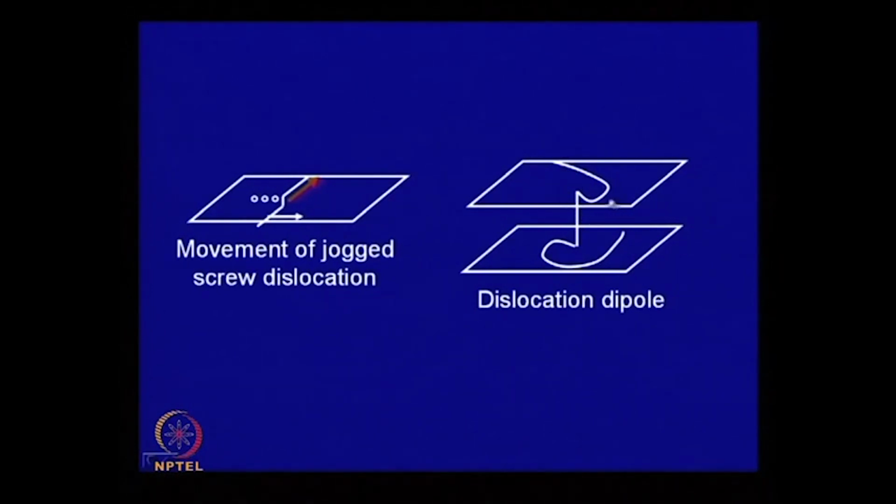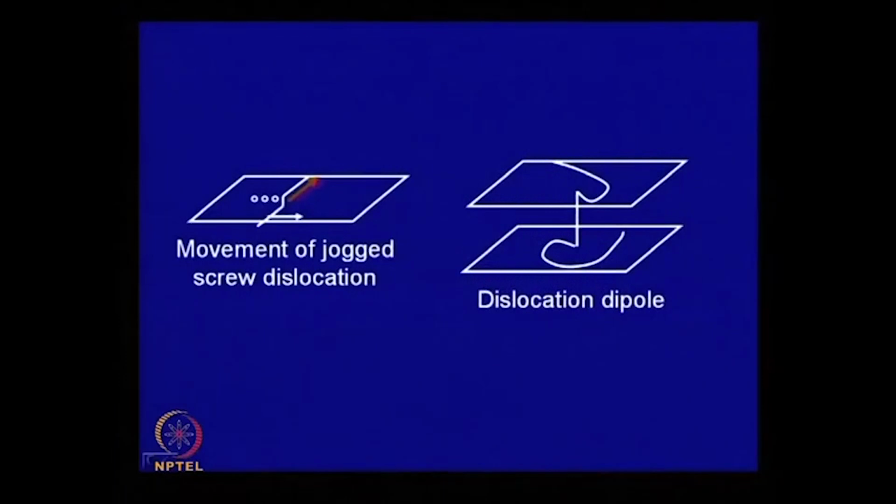But if you continue to pump in and generate more and more dislocations within the crystal, the crystal becomes hard again. So, dislocations can explain both why the yield strength of real crystals is low, and why, as we deform it and the dislocation density increases, there is a lot of dislocation interaction, which makes it strong.